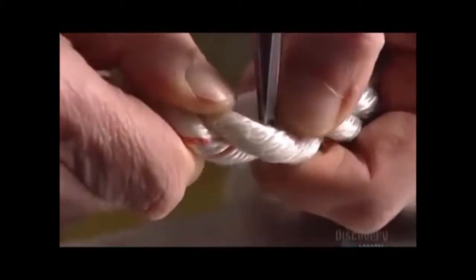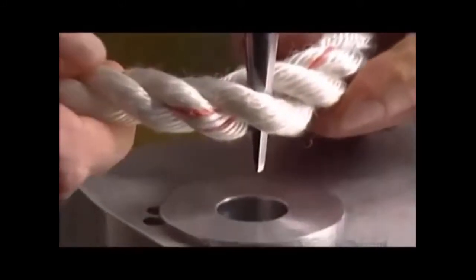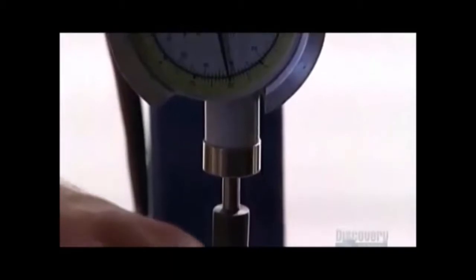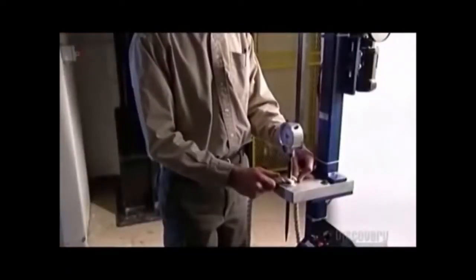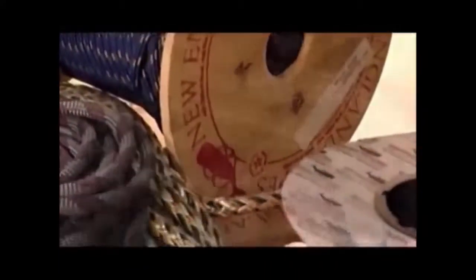Now for another test. They insert a steel probe, known as a fid, into some industrial rope, then place the pointed end into a hole. An electric motor forces the fid through, while a gauge measures the force it takes for it to completely penetrate the rope. It took 4.5 kilograms of pressure to push the probe through the rope, which means this rope is firm yet flexible. So now you really know the ropes about rope.